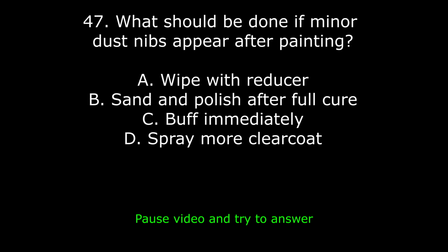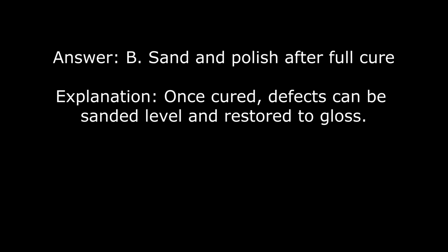47. What should be done if minor dust nibs appear after painting? A. Wipe with reducer. B. Sand and polish after full cure. C. Buff immediately. D. Spray more clear coat. The answer is B. Sand and polish after full cure. Explanation. Once cured, defects can be sanded level and restored to gloss.